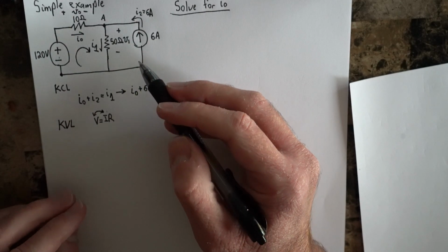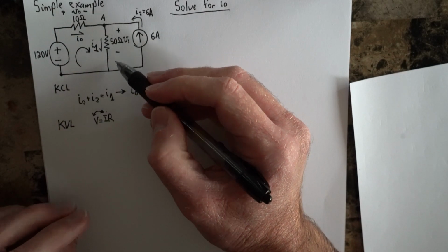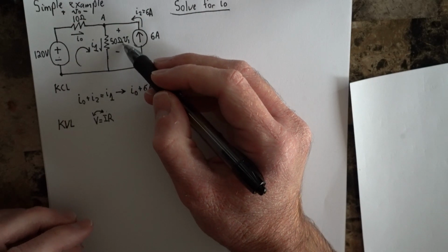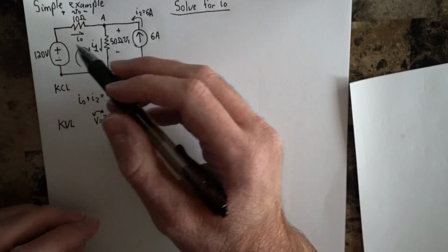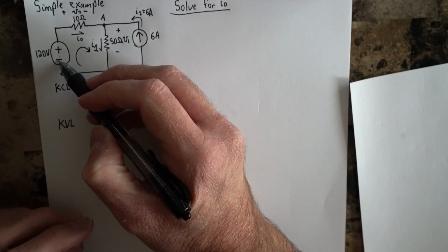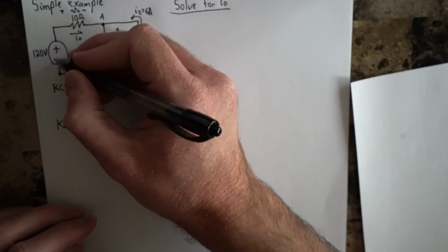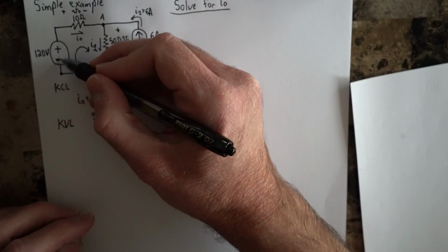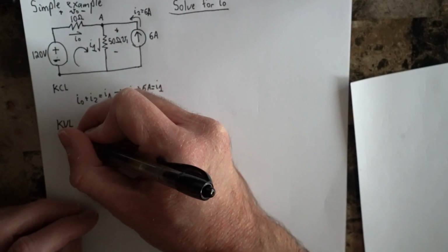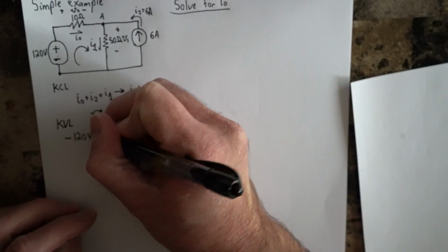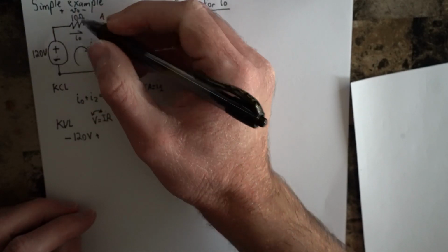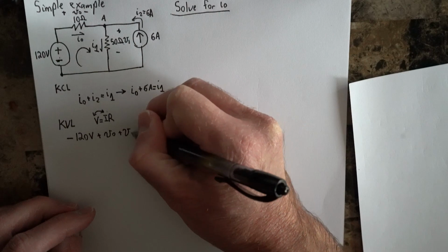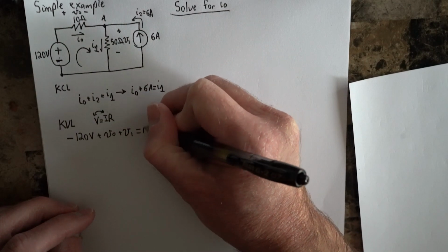Now, again, sometimes you might have problems. You could theoretically do a loop here, but this is kind of a trivial loop because the only voltage that's present here is that of V1, so it doesn't really get us much. But here might prove to be more useful. So let's start here. Again, I'll follow my sign conventions. I've got pluses here, approaching nodes, and a minus here for the source. So starting here, I'll make that loop. I'll hit the 120 volt source. And then we hit a plus sign on the V0. So V0, we hit a plus sign on V1 as we move around our loop, and we've completed our loop. So we set that equal to 0.